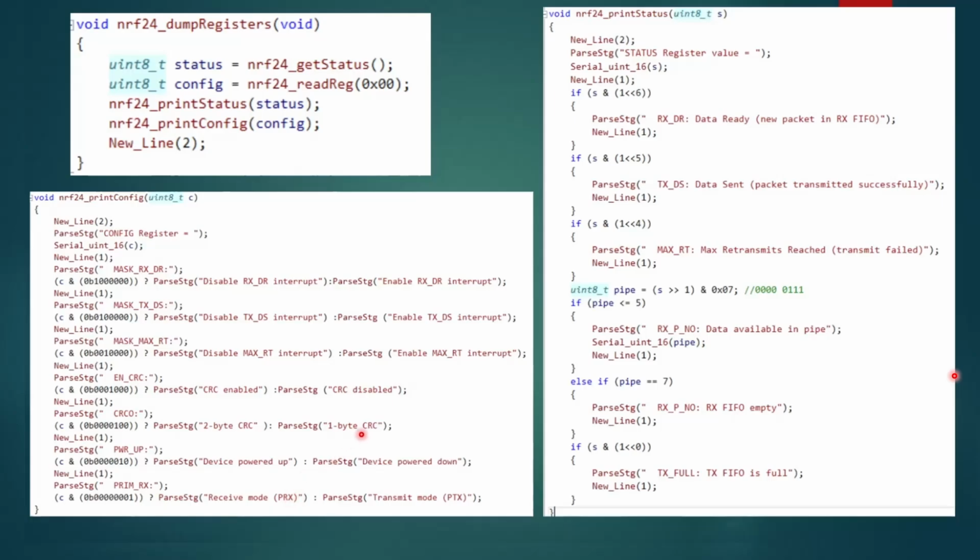So basically what it amounts to is I have my receiver and transmitter, nothing is happening. So first thing I go and look at my status and look at my config. In my config, I'm going to make sure that everything is configured the way it's supposed to be. The receiver and the transmitter better match where they're supposed to match, so we have the transmission. So I would be looking for mismatches on the config, and then on the status, I would look to see what happened. Was the packet transmitted successfully?